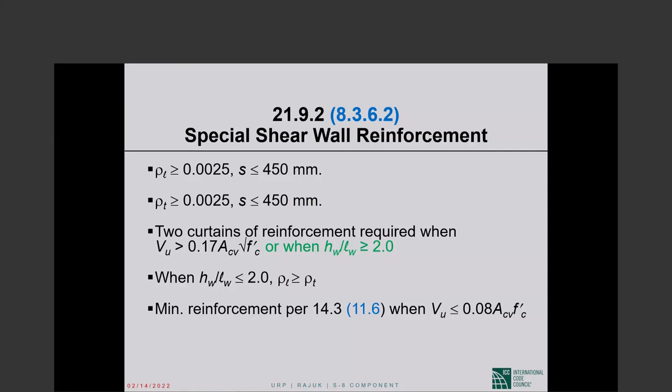Many tests have shown, particularly for low-rise shear walls, that the horizontal shear reinforcement will not do you any good unless it is coupled with vertical shear reinforcement. So we provide not just horizontal shear reinforcement, which is obtained from calculations, but also vertical shear reinforcement to go with it.